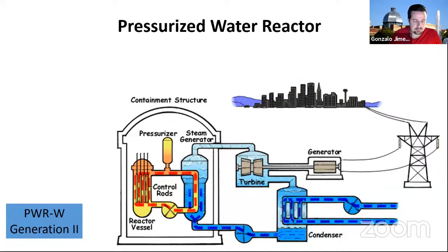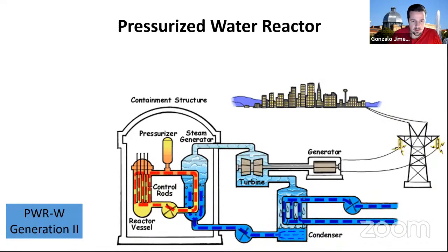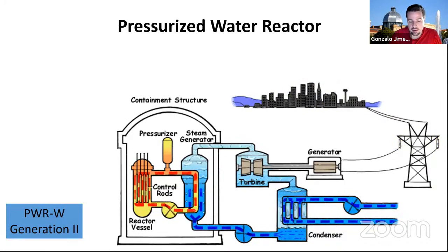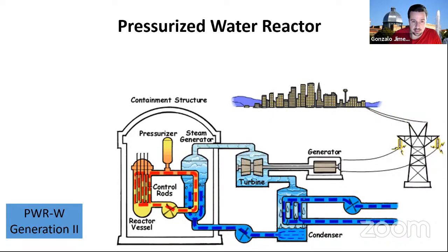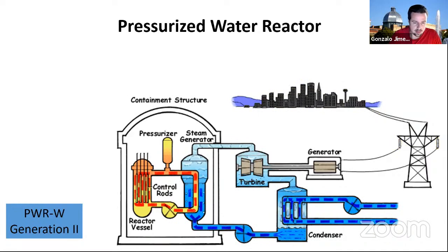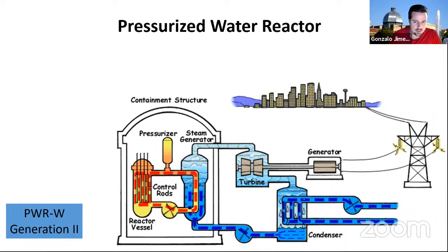Two very important things, because we are going to talk about nuclear safety. One important aspect is that if you have a nuclear operation, of course you need a lot of cooling, but even in the case in which you stop the nuclear fission, you still have a lot of residual heat that you have to cool down. So you will need a lot of safety systems to help you do that.